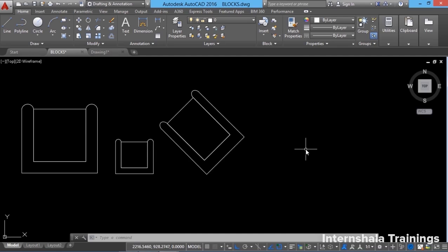So what is a definition? A definition is a hidden object which remains inside the invisible block table area of the drawing database, whereas the reference is a copy taken from the definition. The software establishes a link between the definition and the references, because of which any changes performed on the definition will get instantly reflected on all the references. This procedure is called block redefinition.